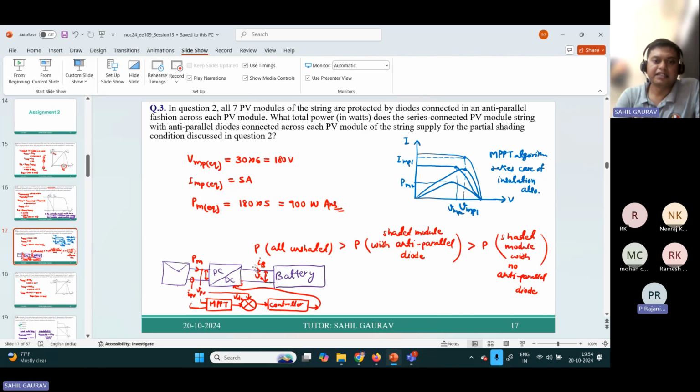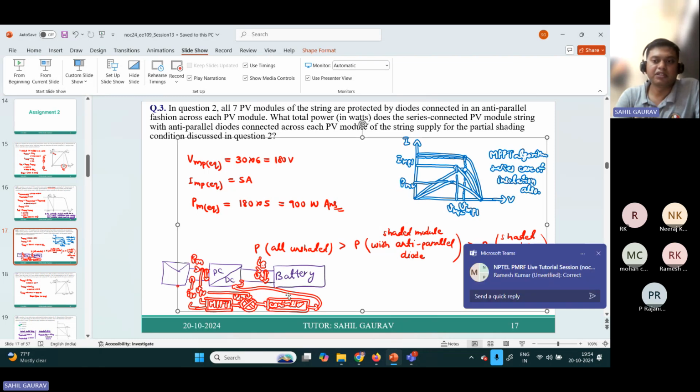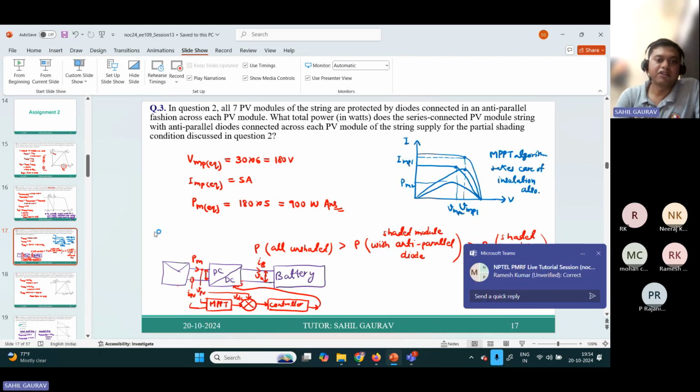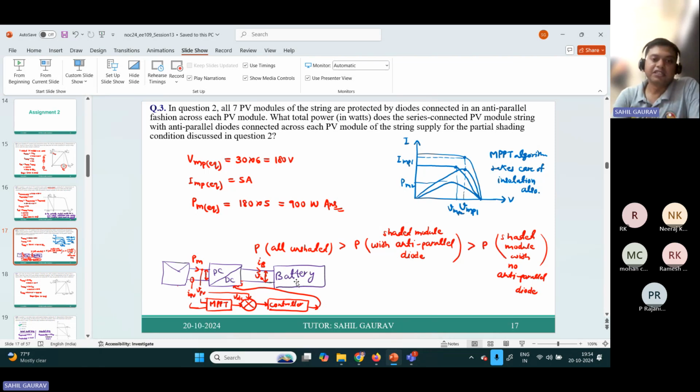Okay, you are saying that this part of the DC-DC voltage is not being obtained. Yeah, I got your point. So this is not the desired voltage, so you cannot set this voltage. Yeah, correct. If this voltage is set by the battery, and the battery SOC is lower, then this voltage is also lower, and based on the converter duty ratio limit, you cannot set this voltage at the maximum power. So in that case, you have to work the PV at a derated MPP.